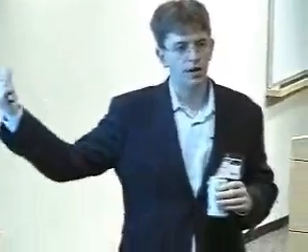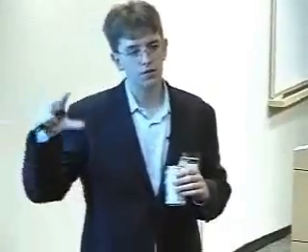Go ahead. So in those collapsed sections, is that where I would learn how multiple threads are going to communicate through the memory system while having the synchronization be well defined? Is that what you're collapsing away? Yeah, that's what I'm collapsing away. We have a memory barrier instruction that interacts with the wave ordering system. So is there basically another scalar value that tells you which thread you're on? Yeah, each data value also carries with it the thread ID of the thread that it belongs to. Okay.